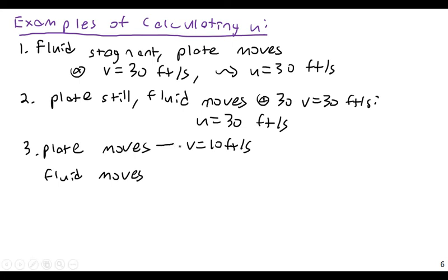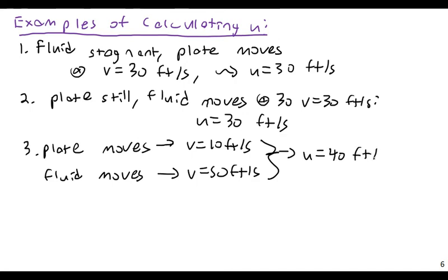So the plate is going to move at 10 feet per second this way, and the fluid moves in the same direction at V equals 50 feet per second. Well here, U would be 40 feet per second. Because again, we're talking about the relative difference between them.